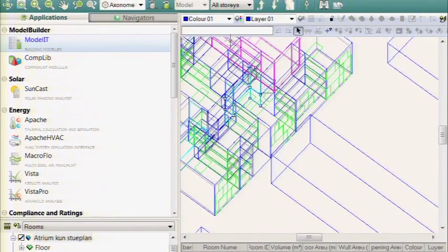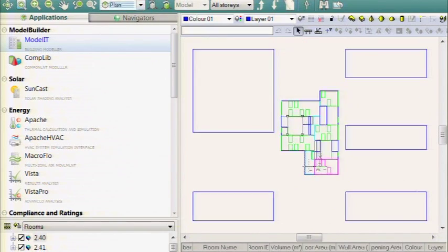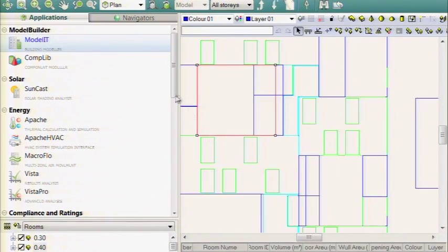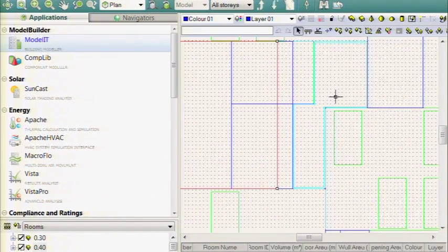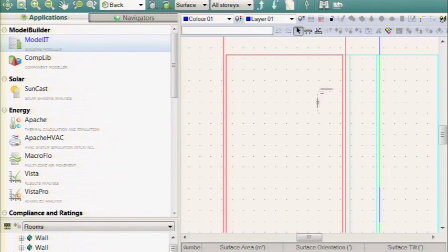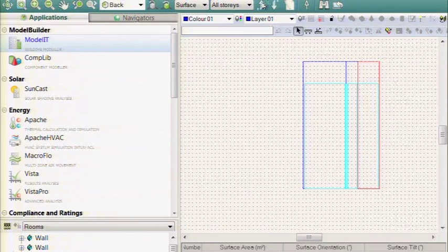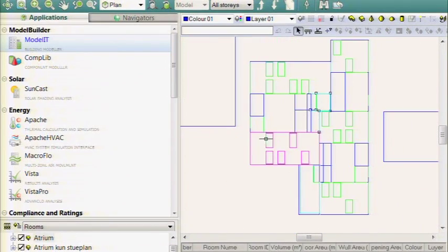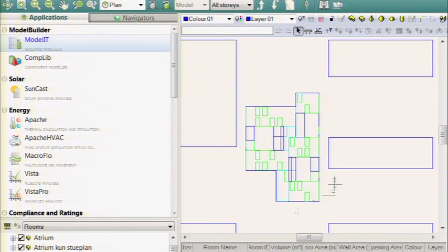So sometimes you can come into the model, and often if I'm going to try to clean this up, I'm automatically just going to turn off all my inner volumes because I want to see what it looks like without it. That's going to give you a much clearer view of your building. You also will have sometimes these weird sliver spaces, and it's just going to be a matter of going in and seeing, do these belong here? Do these not belong here? And going in and saying, is this realistic or not realistic of my building?